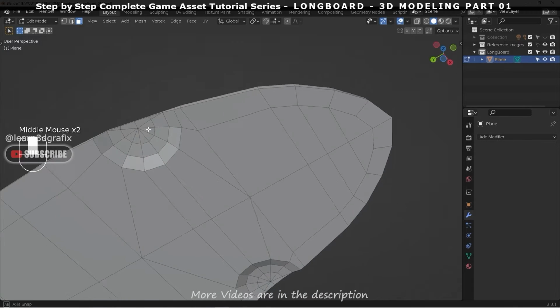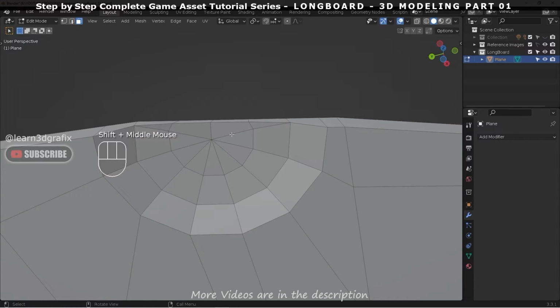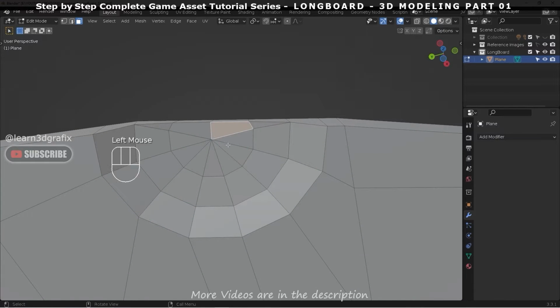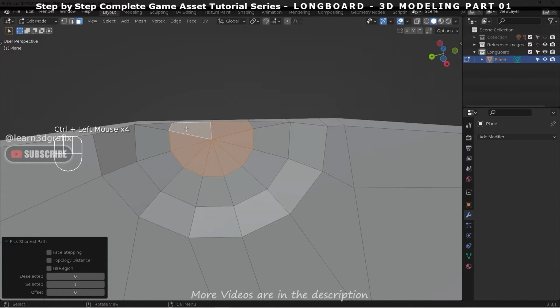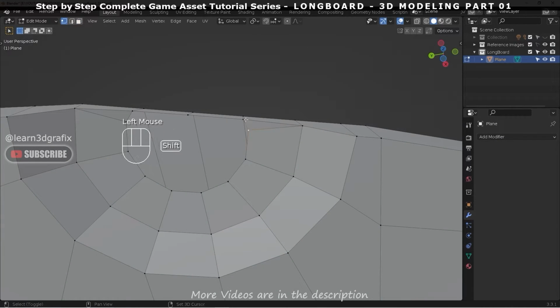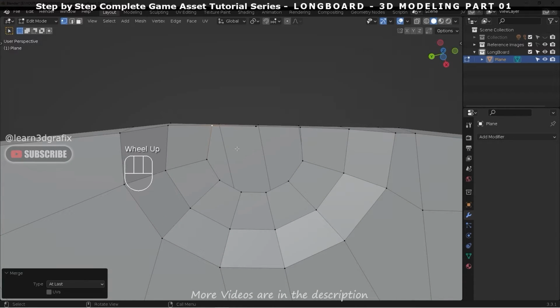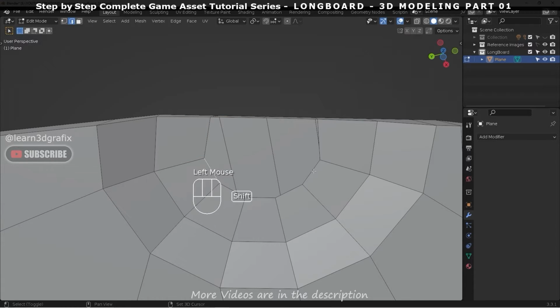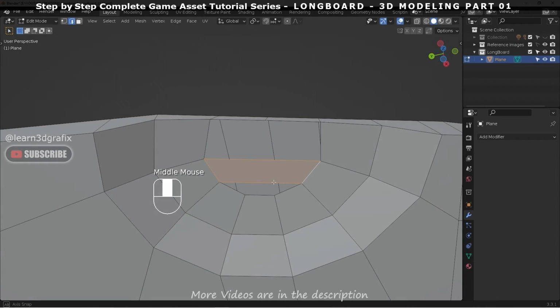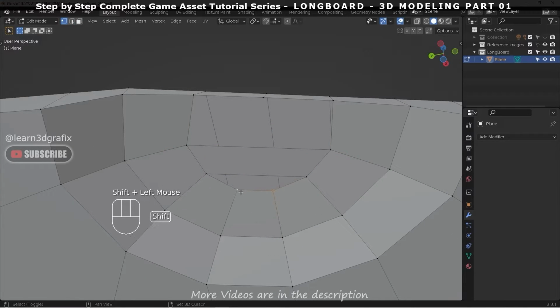We will subdivide the deck later, and before doing that we have to remove these triangles from here, so that the wireframe and shading look clean. Hold down Ctrl and select these polygons and delete them. Hold down Shift and select these two edges and press F to bridge them. Select these two vertices and merge them together.